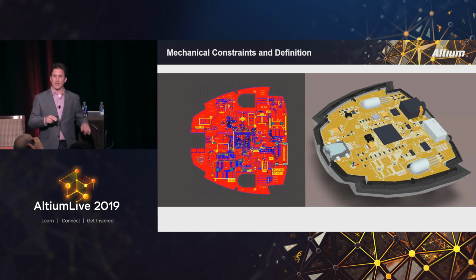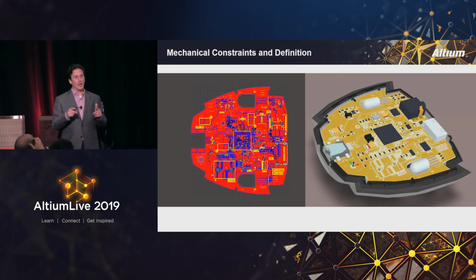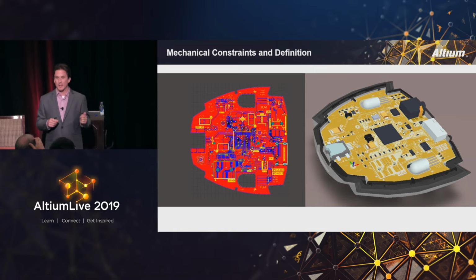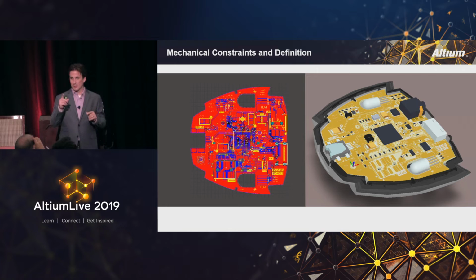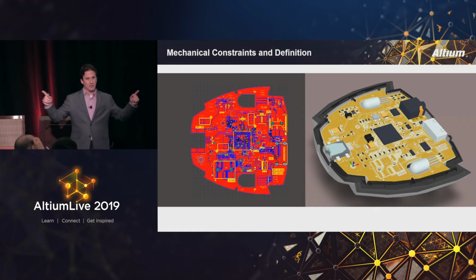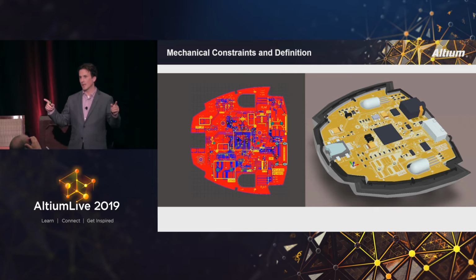If your design has connectors coming off of more than one side of the board, I want you to really pause and think about that. Because if you've got one that's a debug or intermittent connection, you shouldn't have to worry as much. Or a connector to a backplane. Yeah. But what happens when I have connectors coming off of 2 sides of my boards? Now I've got a dipole antenna. And now I'm going to be wrestling a lot more with EMI.